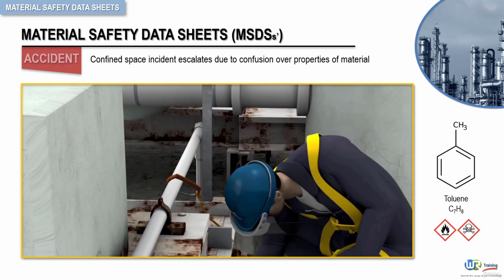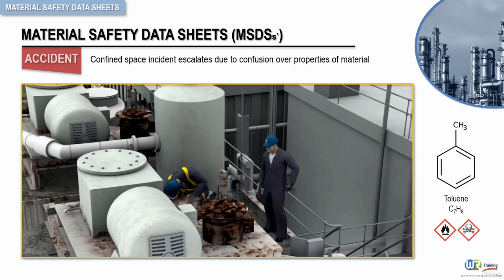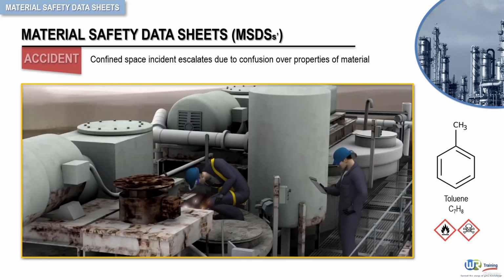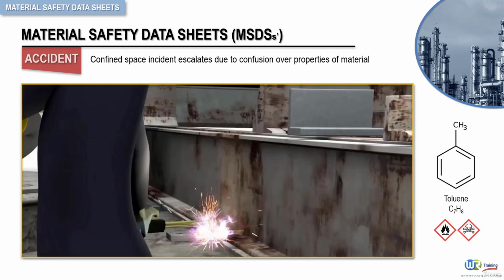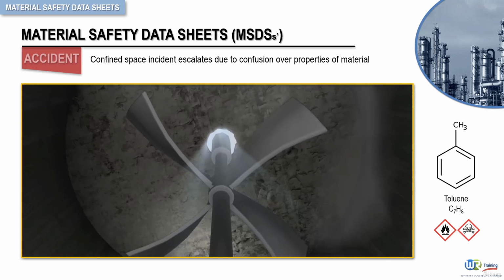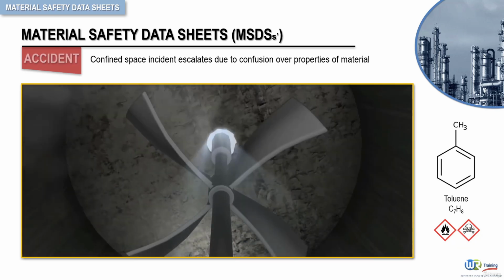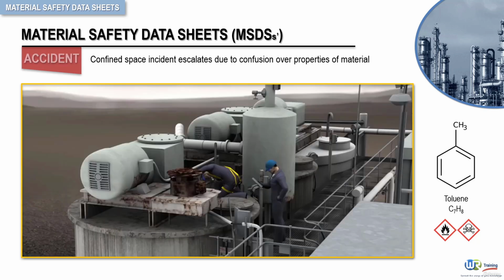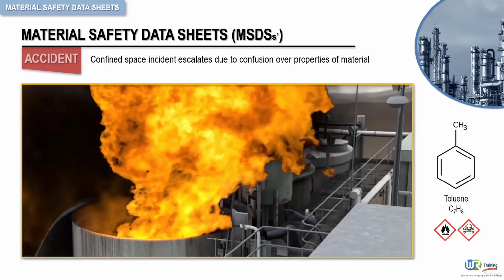He connected his safety harness to the tank's agitator support and worked on top of the tank, as the other operator looked on from the nearby catwalk. But unknown to the operators, flammable toluene vapors were at dangerous levels inside the tank. A hole around the agitator shaft provided a pathway for ignition. Sparks fell into the tank. The ignition of the toluene vapors caused a powerful explosion.